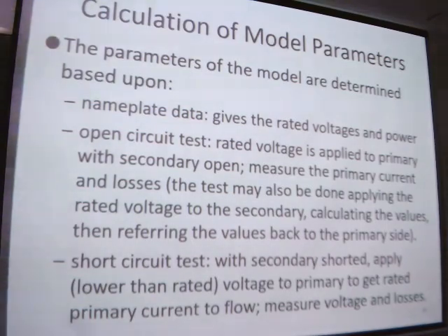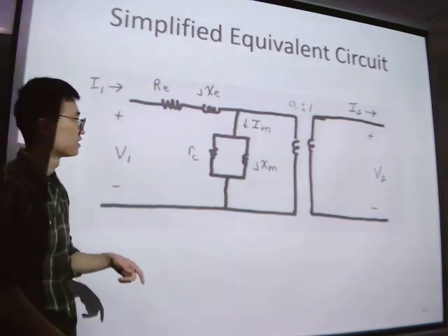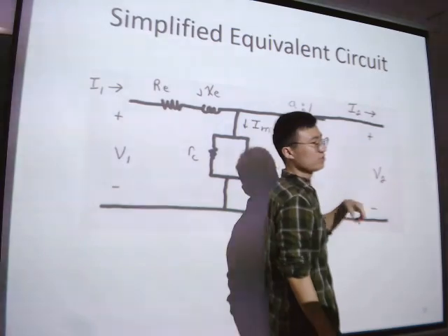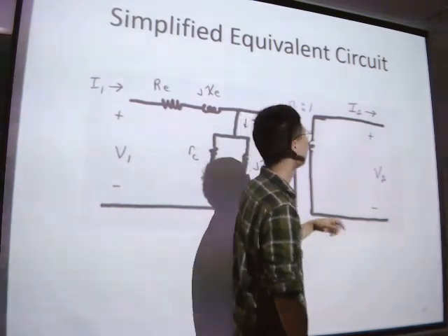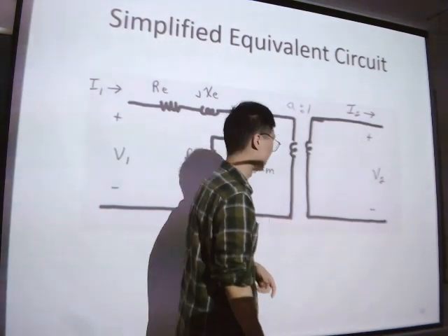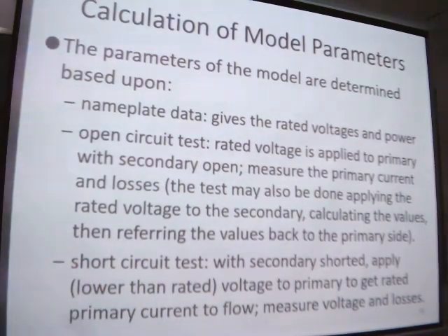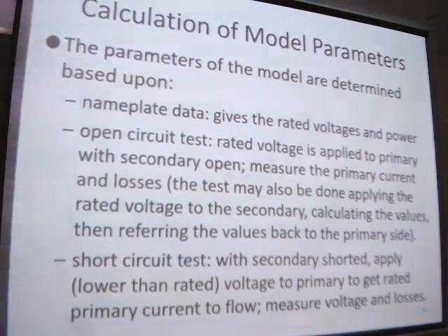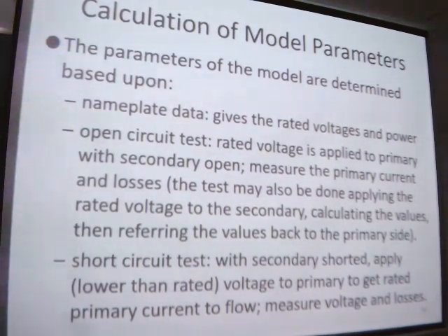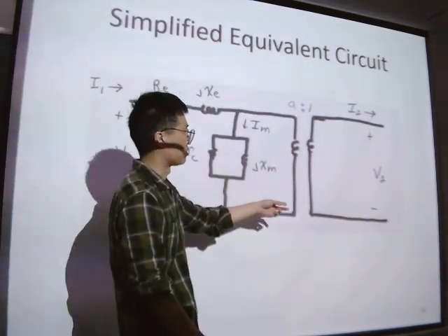And for the second test, the short circuit test, we connect these two points, so I2 is no longer equal to 0. We also apply a voltage, but here we apply a very low voltage because here is the short circuit.